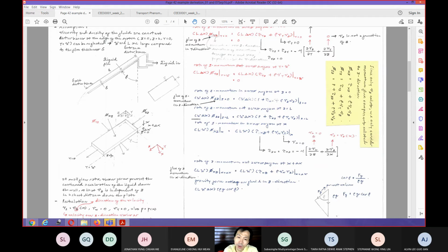So where is the location where z equal 0? The location where z equals 0 is at particular locations in here. So the area where it applies is equal to W multiplied by delta x, and then we multiply that with the tau ZZ. At ZZ is this one, this particular force. And then we need to inspect that one at z equal 0. So that one is W delta x multiplied by the pressure plus tau ZZ plus rho VZ at z equals 0.